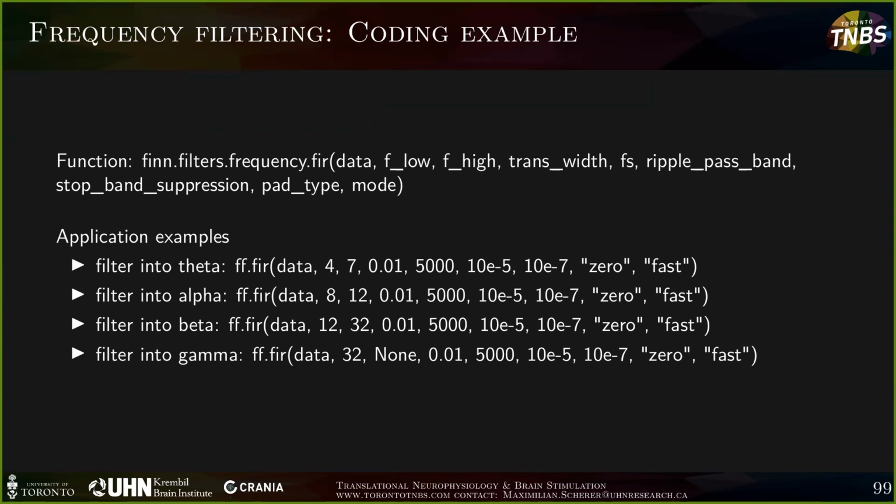The frequency spectrum you're looking at with electrophysiological signals is usually smooth, which means if you cut off a tiny bit of it, that should not have a significant impact on your results. If it does, there's usually something wrong with the analysis in the first place.